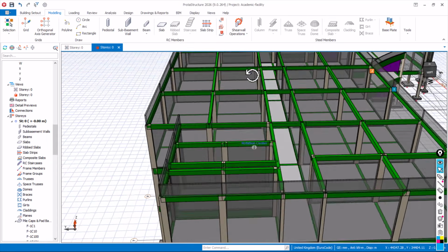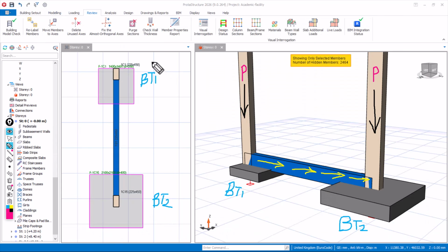Let's now begin on the strap footing design. In the concept of a strap beam design, the load on footing type 1, which is an eccentric footing, is being transferred to the footing base of footing type 2, as you can see here. Now let's assume that this is the load, which is P, on footing type 1. Based on this eccentric footing that you are seeing here, there is going to be an overturning moment around this place, because the load is now centered at one particular edge and no more at the center.